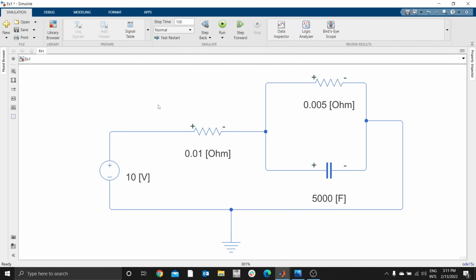Okay, we have modeled our battery equivalence RC circuit, but we have used 10 for ease of display. Then, as I said, we have various types of domains. This one is the electrical domain that has blue lines. For us now to get the current here, we need a sensor. At this sensor, we can only read the signal in another domain called the Simulink domain, a Simulink signal. This one is a physical signal because you are using the actual building blocks.